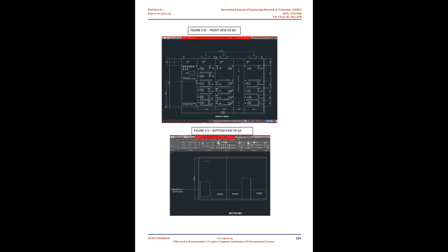The induction motor can be made to operate on leading power factor like an overexcited synchronous motor. Phase advancers have an advantage because the exciting ampere turns are supplied at slip frequency. Therefore the lagging kVA drawn by the motor is considerably reduced. Phase advancers can be conveniently used where the use of synchronous motors is inadmissible. However, the primary disadvantage of phase advancers is that they are not economical for motors below 200 HP. 4. Proposed method.